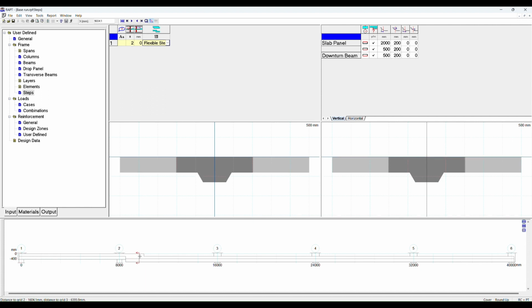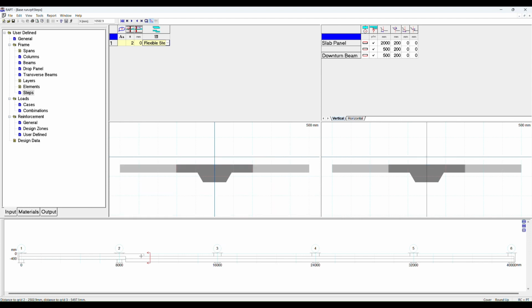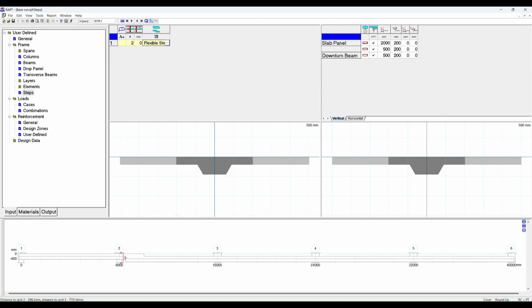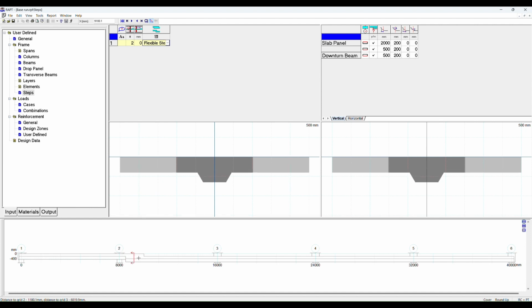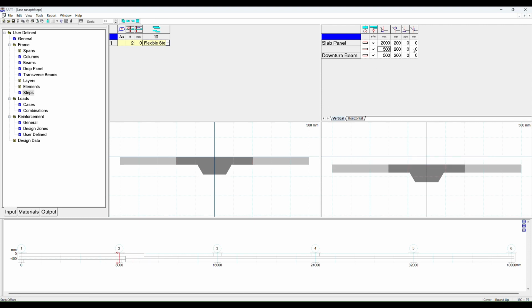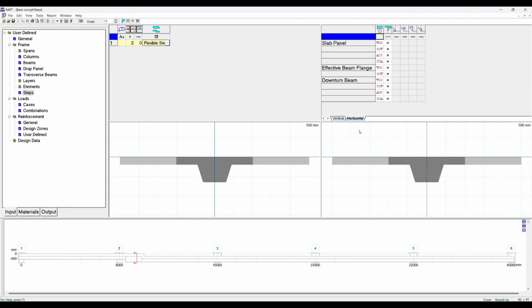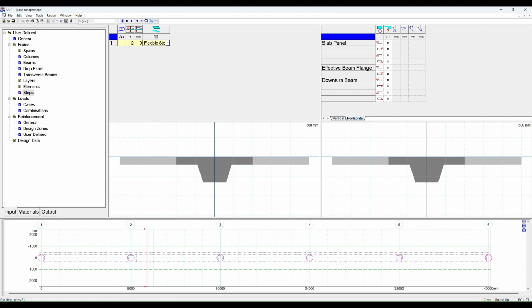And if we look at the sections, from one section we go to a thickening, and the thickening then stops at this location here. Now you probably would have the slab stepping at a much tighter distance, so we can do that. And let's just add this to be, say, 1800, so that it's a 200 wide step in the slab.